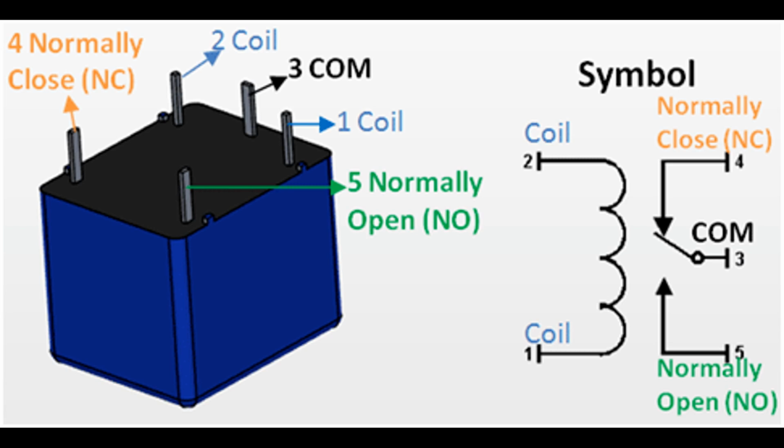Power distribution. Relays are utilized for power distribution and switching applications in industrial control panels and electrical distribution boards. They enable the selective switching of electrical loads, circuits, and power sources, allowing for efficient power management and distribution within industrial facilities. Relays help prevent overloads, short circuits, and other electrical faults by isolating faulty circuits and disconnecting power when necessary.